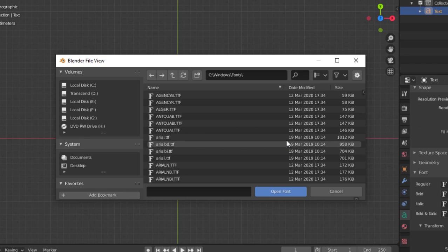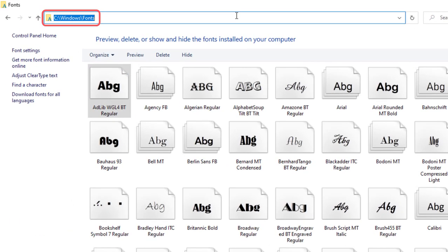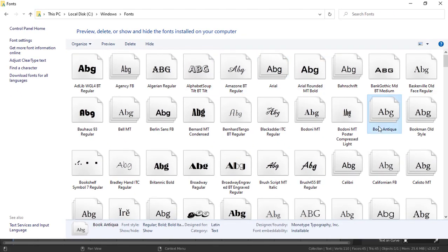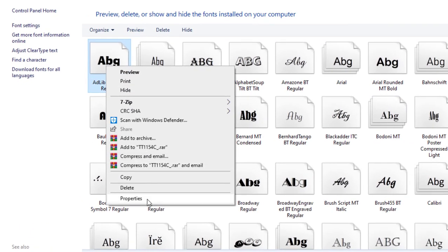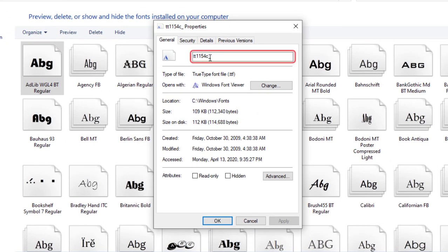First you must make sure you are in this location. We need to see the font styles and choose a font for this theme. Therefore, open this location in your File Explorer. Now you can see it shows the fonts with their styles. Scroll down and see what type of font you need. Now select a font and right-click it, and go to the properties of the font file. Now copy the name of the font, and minimize or close the File Explorer, and move into Blender.